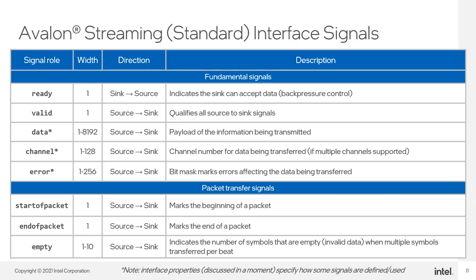Note that when creating custom components with Avalon Streaming interfaces, you don't have to use all the signals listed. Only use the signals that are needed to implement the desired functionality.